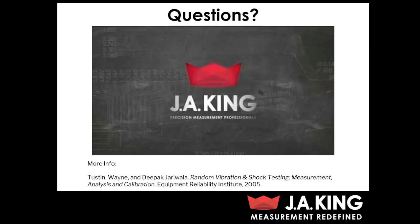Okay. Someone wants to know if you can use the solar boxes for things other than automotive parts, such as items that would be visible in your home through a window or something of that nature. Yes, definitely. So solar boxes can be used for more than just automotive interior components. Really anything that's going to be used behind any sort of glass, we can create a solar box for. And like I talked about in deciding the parameters of these solar boxes, the way we would do that is just take some field data, figure out the correct angle of orientation, temperature, humidity, and we would use all that data to create a solar box.